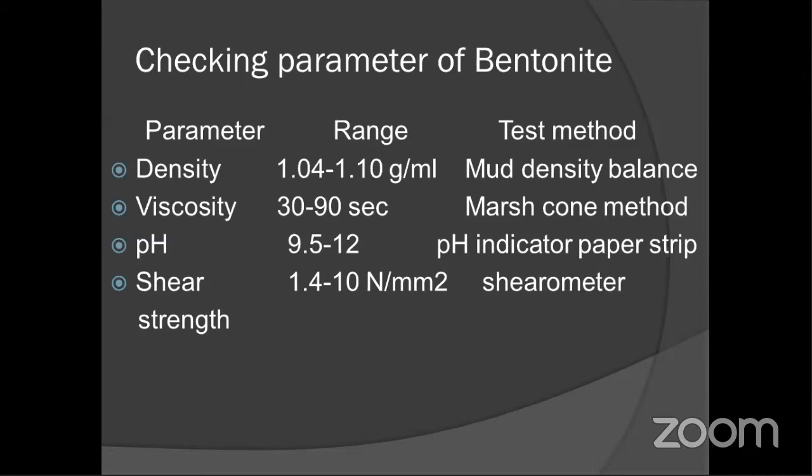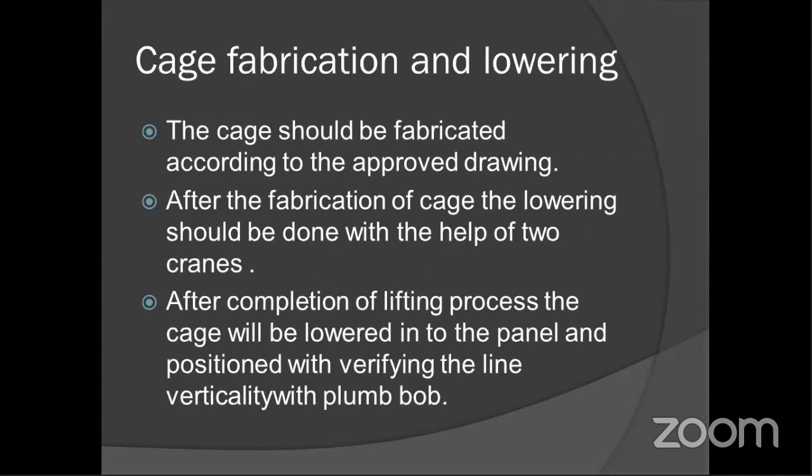Regular testing programs should be conducted, like slurry fully mixed, funnel viscosity, filtration, and specific gravity, where everything should be checked properly for the bentonite when we are going to use it. Especially density, viscosity, and specific gravity, everything should be proper so that it will be effective for us.